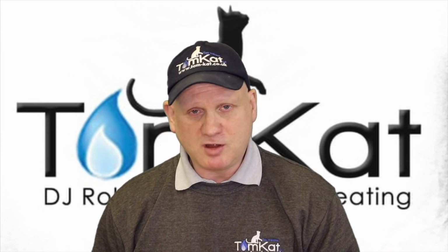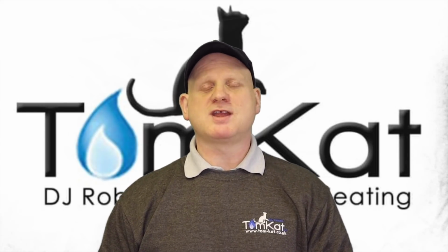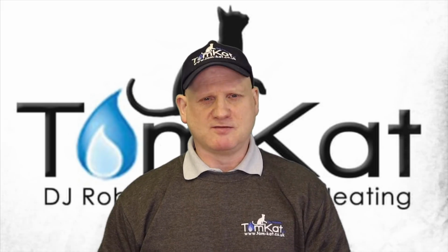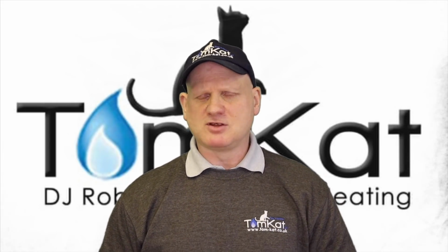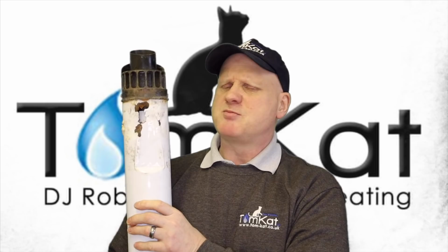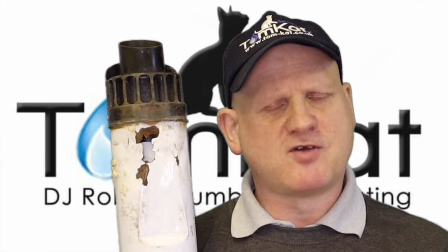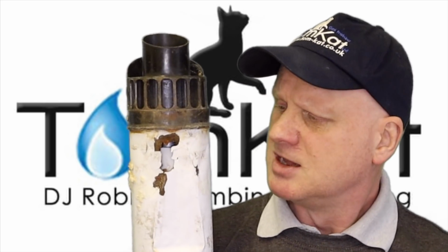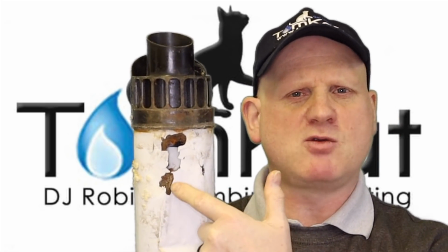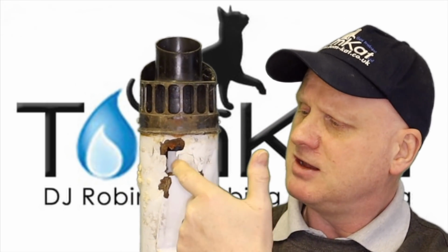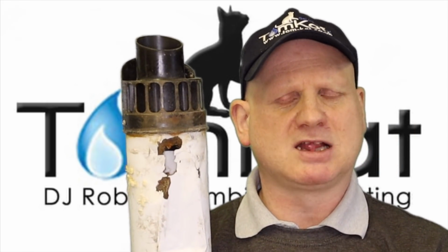So why is it important that Baxi and Ideal flues don't stick out too far? Well, really, you don't want any flue sticking out too far. But the reason why these two flues can't stick out is because this could happen. Now, these flues aren't protected from UV rays. So what could happen is the outer skin, which is the air inlet, as we now found out, could actually go and rot the metal away.